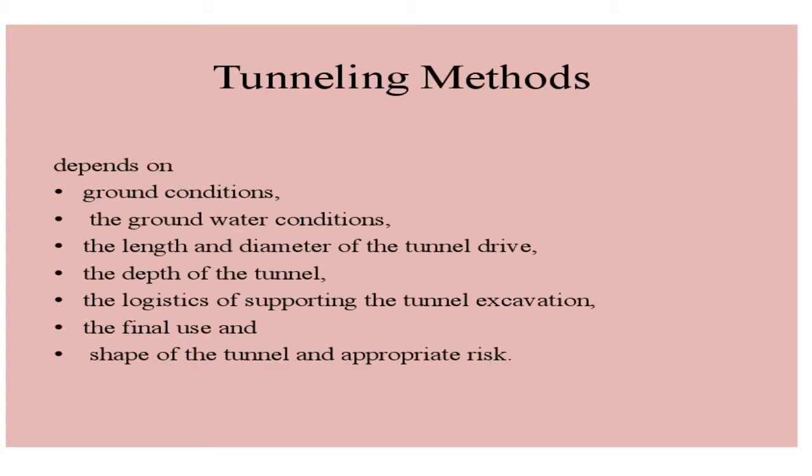Now coming to the factors on which tunneling methods depend: ground conditions, groundwater conditions, the length and diameter of the tunnel drive, the depth of the tunnel, the logistics of supporting the tunnel excavation, the final use and shape of the tunnel, and appropriate risk. So these are some factors on which the tunneling methods depend.